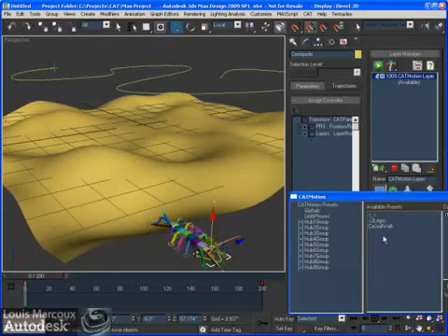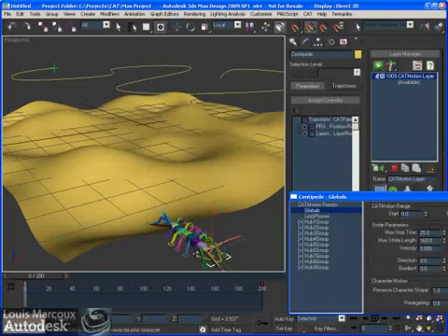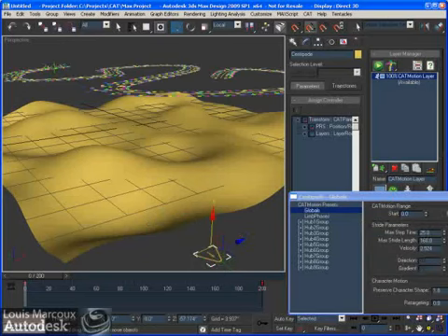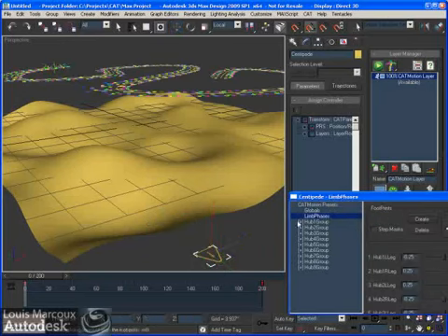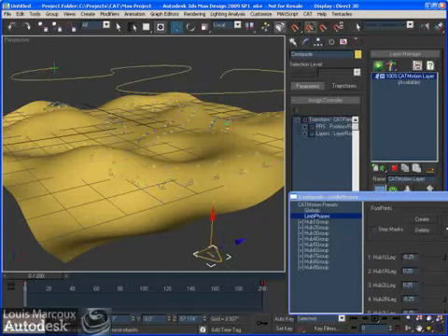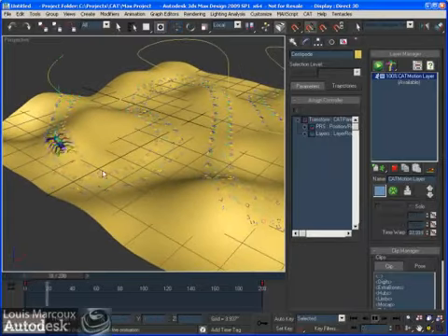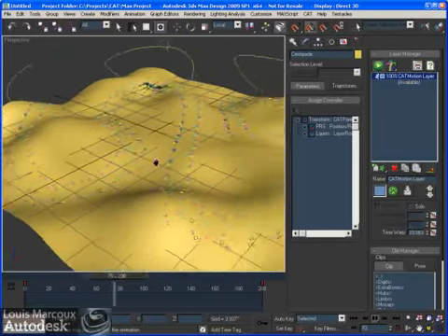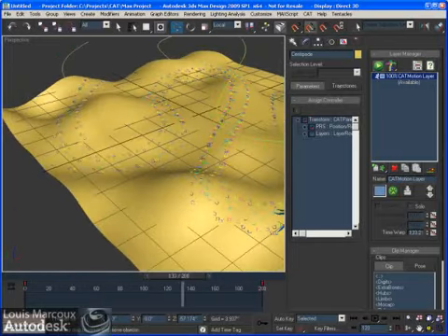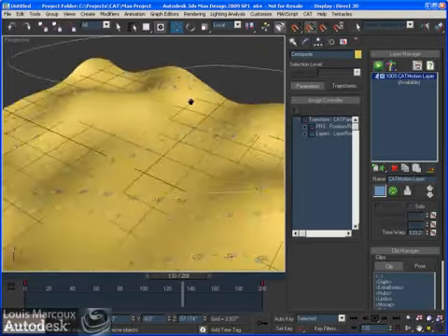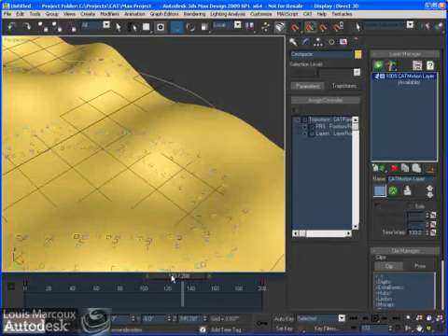So again, cat motion. I'm going to go to the global. I'm going to grab this path node, and I'm going to pick the ground as well. And now we're going to have it follow the ground. So if I play this now, you'll see that this is following the ground like that. And where it breaks, or where it's a bit less interesting, is when you get into those areas where you get very strong curves.